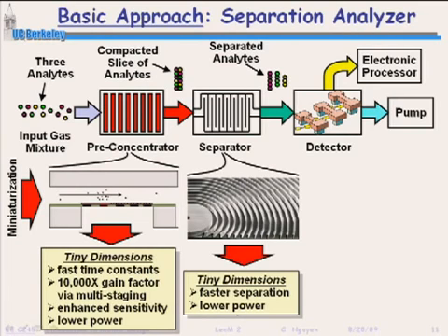When a gas molecule or several gas molecules impinge on that beam, absorbing to the surface, that changes the resonance frequency. You detect that shift in frequency as the presence of that particle. And it turns out we can detect shifts in frequency much better than we can detect changes in voltage levels. That's why resonant sensors are some of the best around.